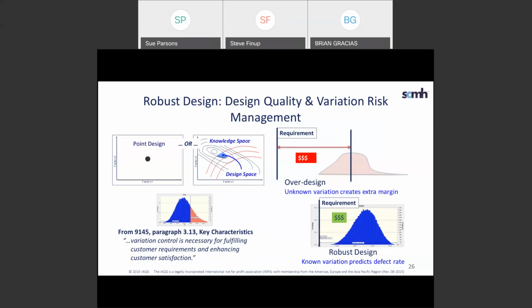It helps you quantify product capability, much like process capability is measured by things like CP and CPK. So product capability really equates to a measure of design quality. So the benefit is that you can actually provide visibility to reducing unneeded over-design margin, which adds to customer value and adds to the value in the business. And finally, it allows you to introduce manufacturing suppliers' capabilities from their processes, which can help enhance the creation of material and dimensional requirements by a better understanding of variation.